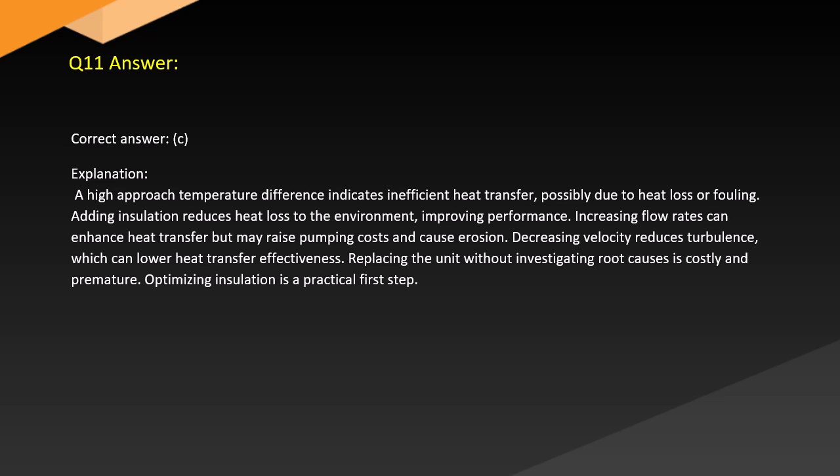Increasing flow rates can enhance heat transfer but may raise pumping costs and cause erosion. Decreasing velocity reduces turbulence, which can lower heat transfer effectiveness. Replacing the unit without investigating root causes is costly and premature. Optimizing insulation is a practical first step.